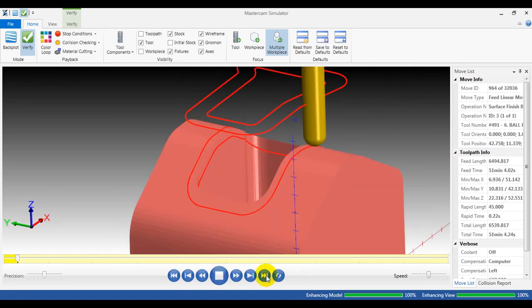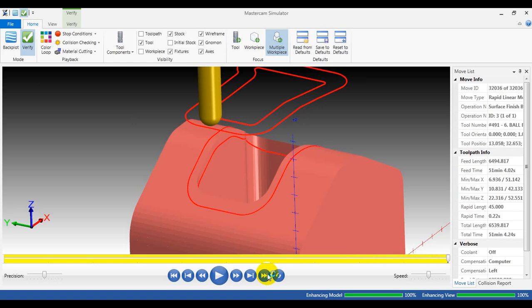Okay, fast forward just to see the result. For a surface like this, you have two options. You can select the Flowline toolpath or you can select the plane toolpath, but the plane toolpath works great only if you know how to control the curve.